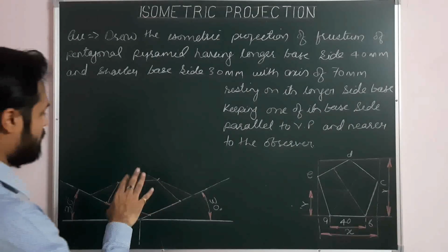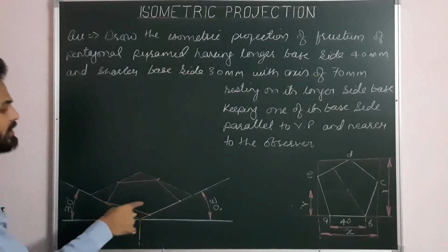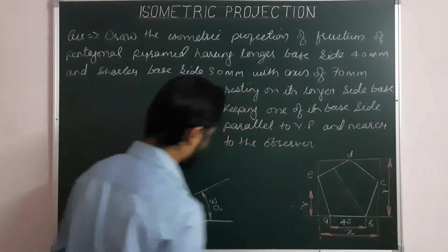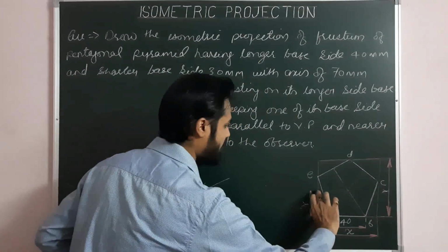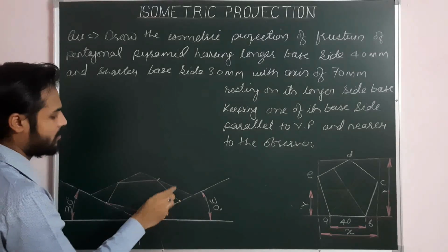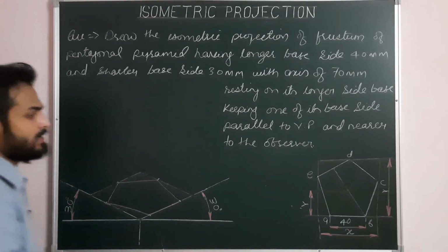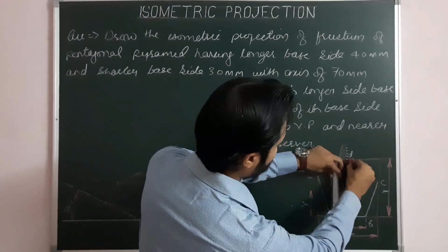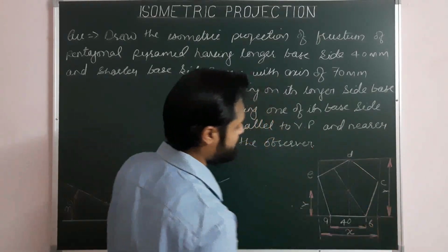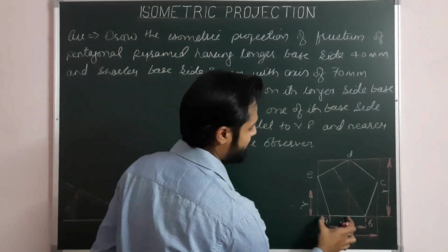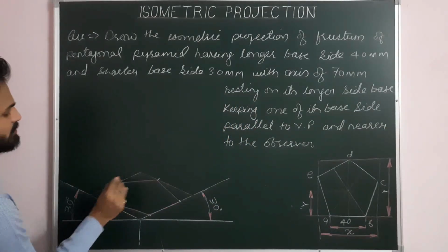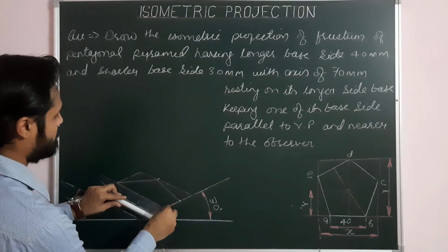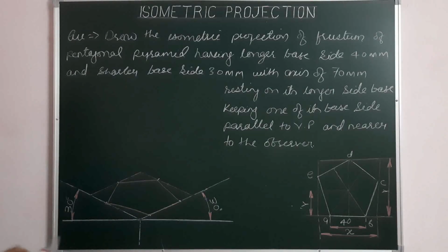Next, we have to locate the center here on the isometric plane. So, taking y dash along the second ISO axis, a line from D will pass through the center. Or for regular geometry, we know that this gap is half of x. So from this point to the midpoint of the side, drawing center lines.